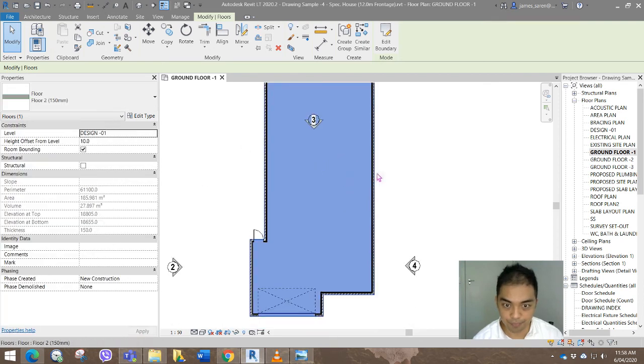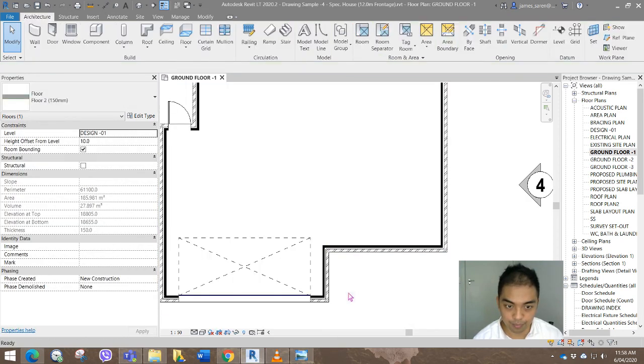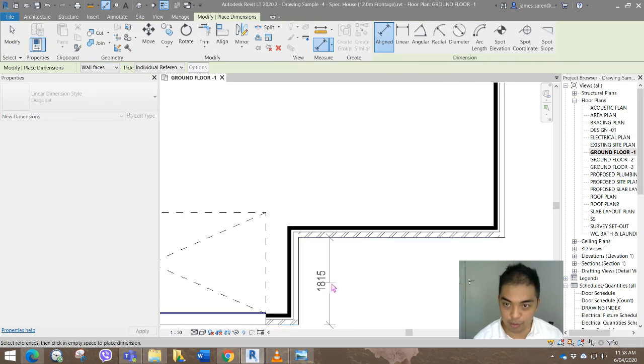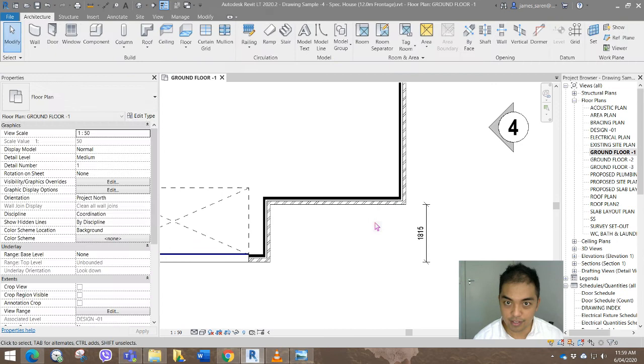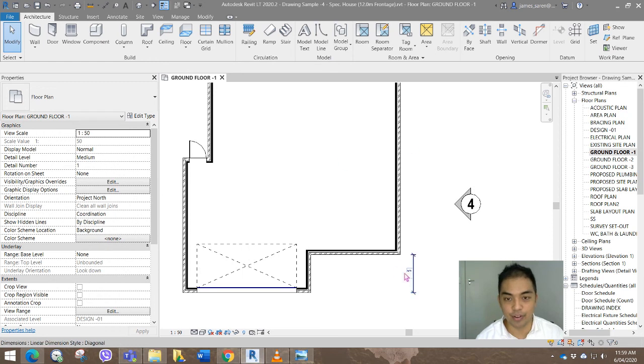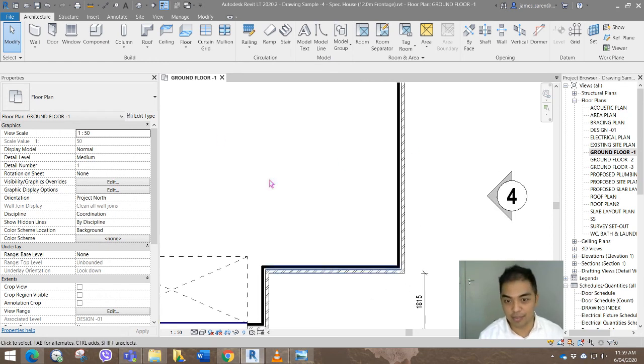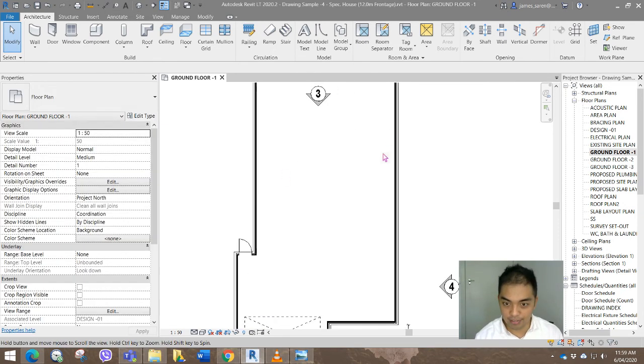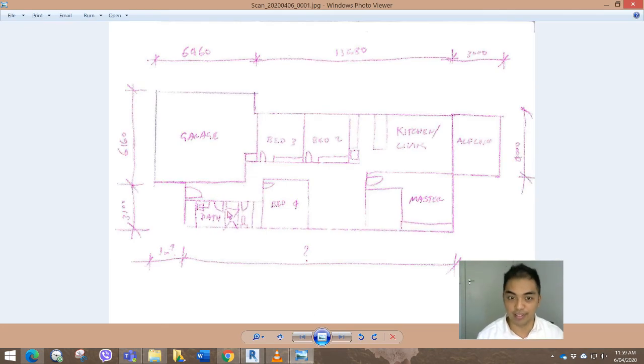So you could even bring that in just a smidge or adjust accordingly. The builder wanted roughly 1 meter. It's got 1.8. If we brought that forward, it would bring the square meters up, because if we're extending that area, so that wouldn't be good. So then this is the part where we start fiddling, we start playing to add all these walls. So yeah, I'll first go 3 meters by 4.